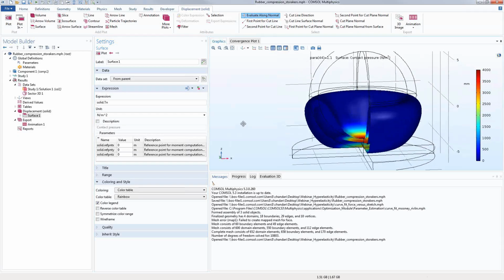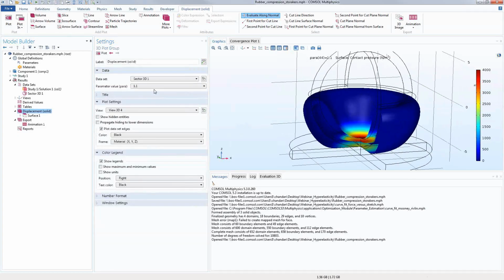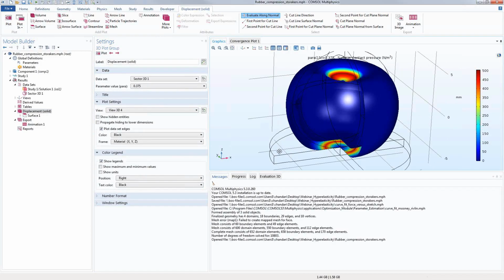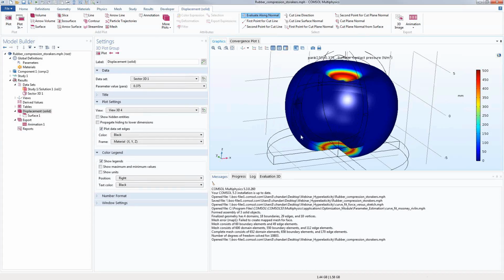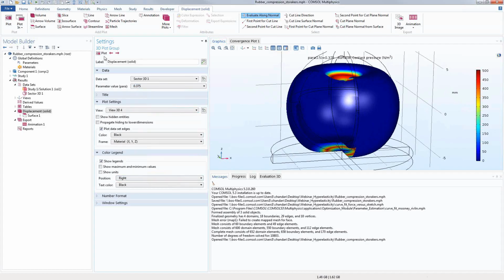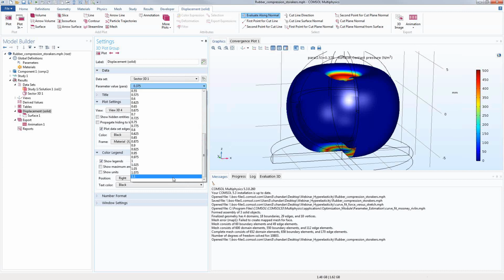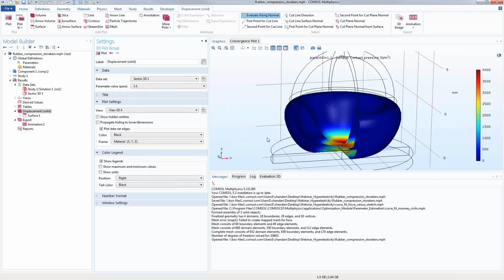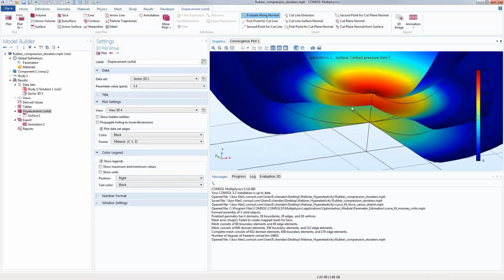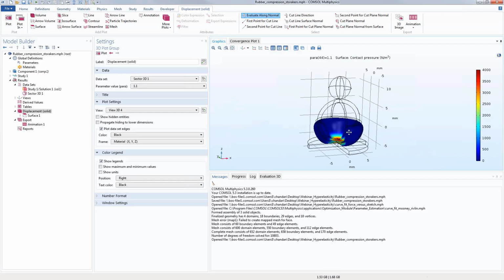And let's see here. What you're looking at is, initially, when there is no self-contact, you basically have the contact pressure between the spherical shell and the indenters. That's why you see only two colored regions for two contact surfaces. But as soon as you have self-contact at the end, you should see three such colored surfaces right there: one at the top, one at the bottom, and one for the inner surface of the spherical shell. And you can compute the contact pressure there.